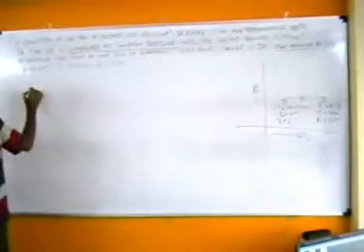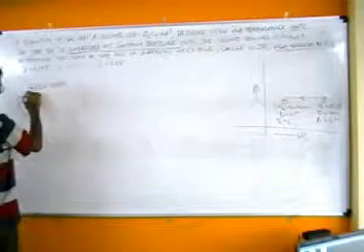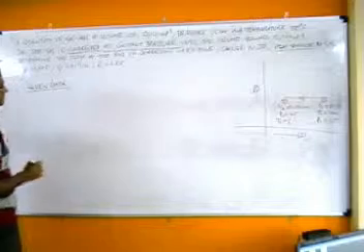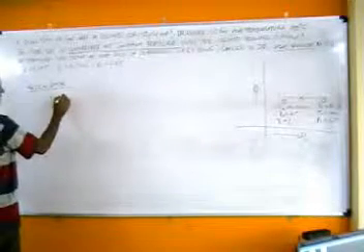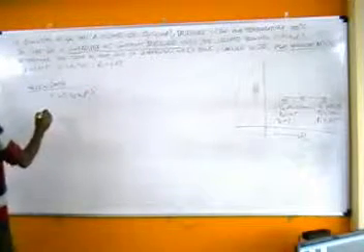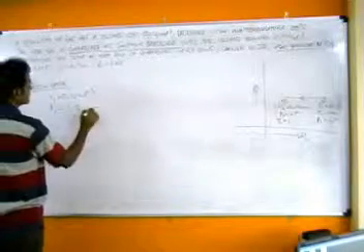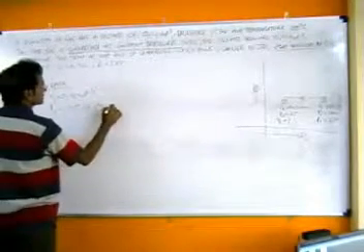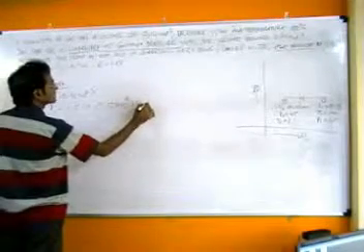So if we take down the given data, the data must always be converted into SI units. The initial values are V1 equals 0.14 meter cube and the pressure P1 is 1.5 bar. You make sure that immediately you convert it into Newton per meter square.